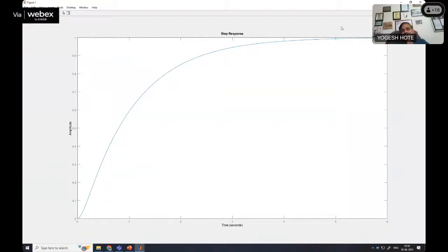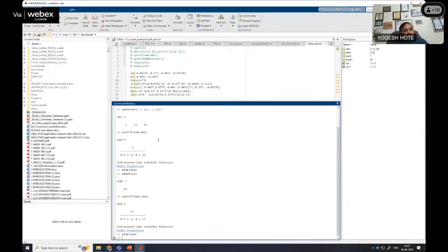Is it okay, Dr. K. Ramesh? Correct, sir. Okay, 1. So now this is a second order plant. I want to determine the response, that is, we have to reduce the model to first order. So the first order pole is at s plus 1. Now we will determine the reduced order model. We discard 10, keeping only 1. My numerator is 10, but my denominator is changed. The denominator is s plus 1 only, because 10 we have discarded.